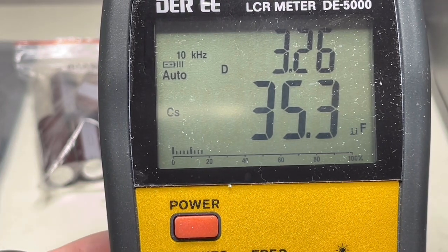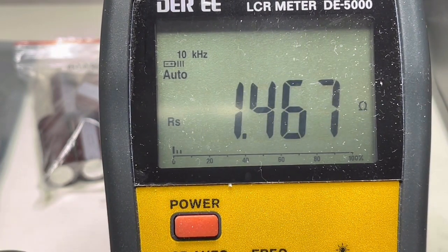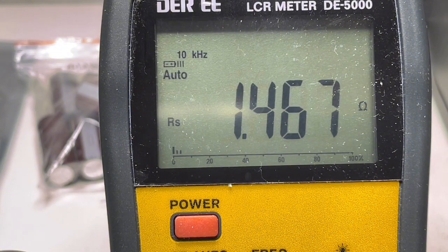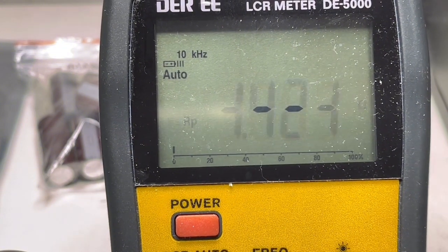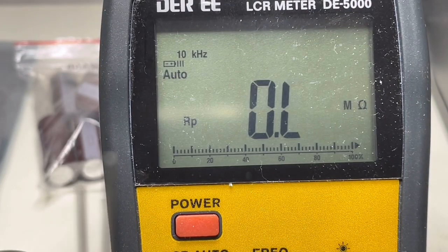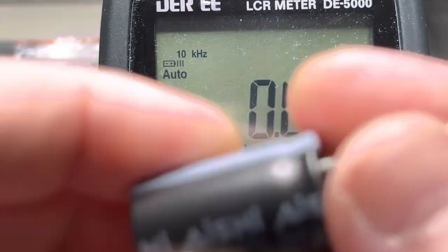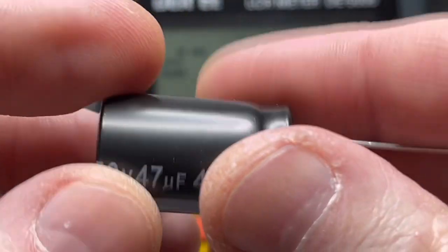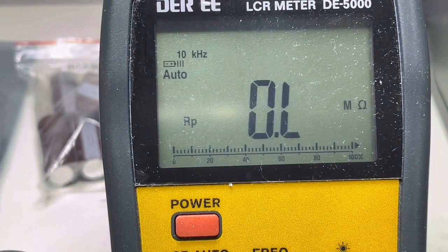We have already 1.46 ohm resistance. Now, to get the 22 microfarads at 950 volts, you have to put 2 of them in series. That means you will get up to 3 ohms of ESR. And you don't believe me? Wait.